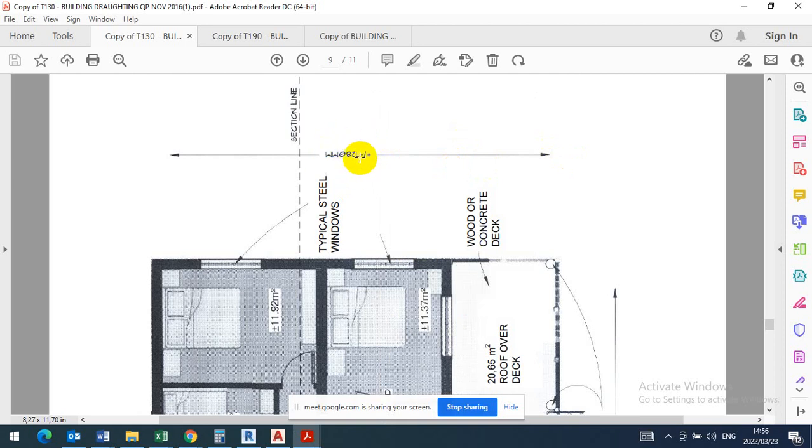Plus or minus 7280 millimeters. When they tell you that the length from here to here is this plus or minus, they're saying it needs to be at least around 7,280. So what I expect students to do is to go exactly to this. It's better you are perfect. Go to 7,280. That will be from corner to corner. You include the bricks. Are we together? Yes.